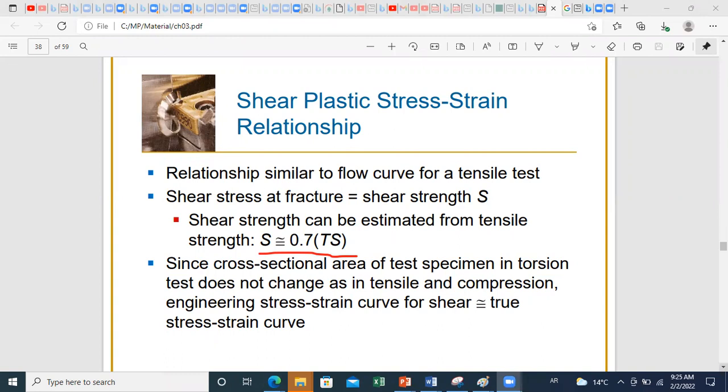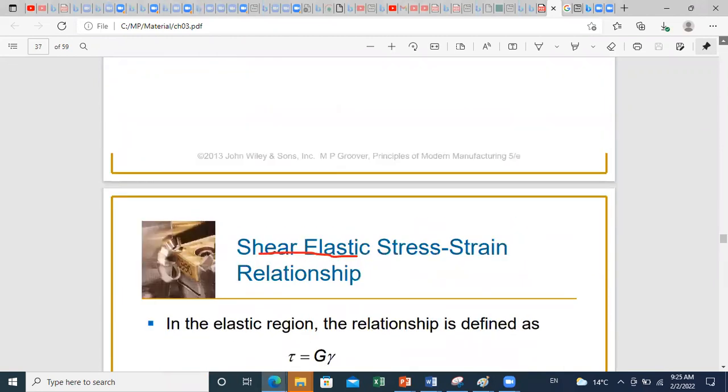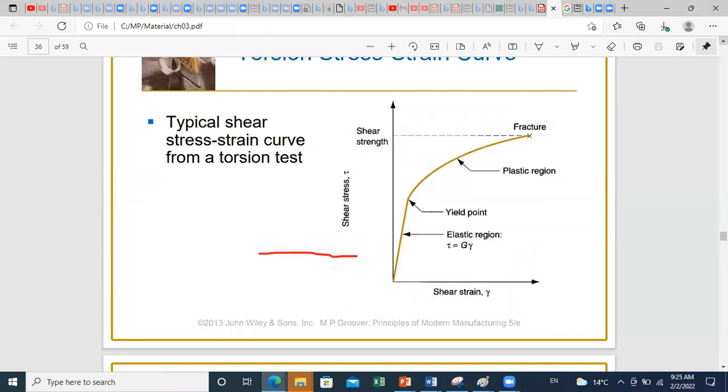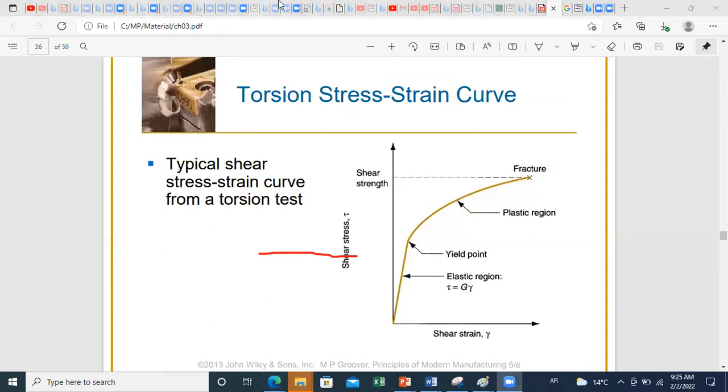Doctor, in the previous slide there was a decrease in slope because less force is needed, right? No, look, it's not that less force is needed. You still need to increase the force, but the rate of increase of the force is lower. Look, the shear is always increasing as you progress. You will always need to increase your force because shear is force over area. Since the area is constant, the variation of shear will represent the variation of the force applied. As you can see, the increase is continuous, but the rate of this increase is variable.